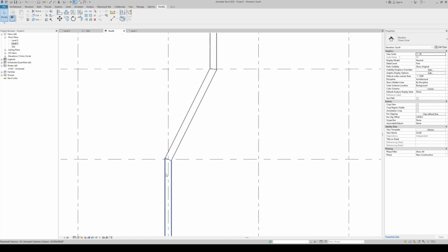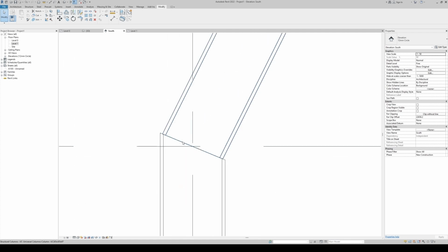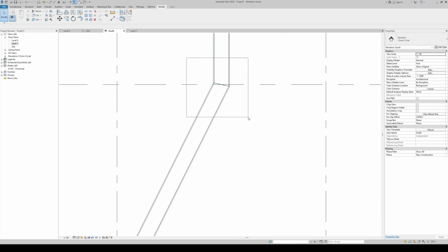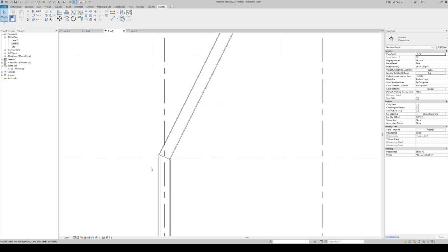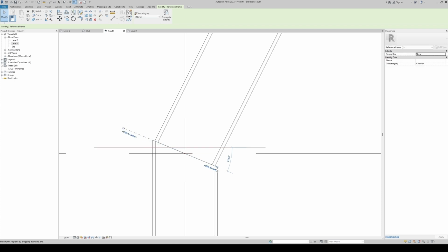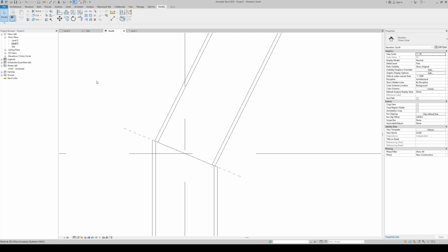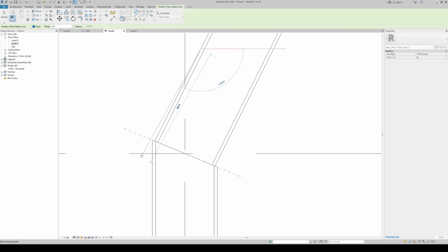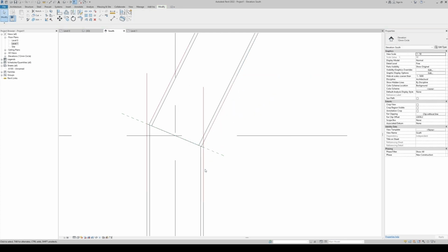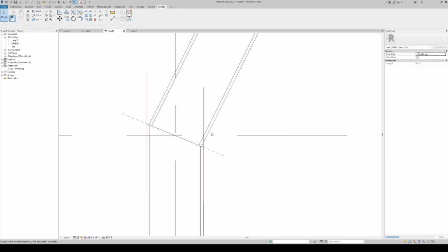It all looks fine, but you need to readjust this point. So here we took an example adjusting this area, but we deleted the reference plane. You can avoid deleting the reference plane. Instead, what you can do is you can just unjoin them, or you can create some lines. Let's suppose I'm creating some additional lines again. So these are the exterior lines of the column, and let us isolate these lines.